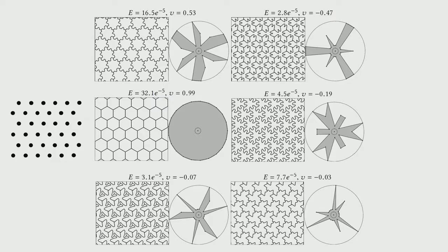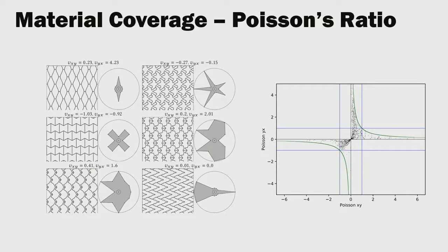And these are all relative values. It's not really a Young's modulus of 10 to the minus 5. It's just compared to a solid material, it's almost 5 orders of magnitude softer. And you can also get very, very different Poisson ratios using this approach. Speaking of Poisson ratio, probably the most interesting, what we see a lot in publications in material science are negative Poisson ratio materials, like auxetic materials. And this plot here shows that our method actually captures a pretty interesting range of strongly auxetic materials, with values going up to -4.